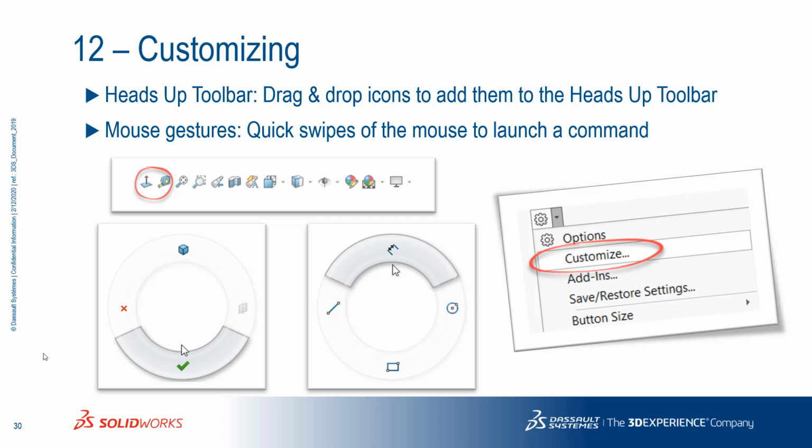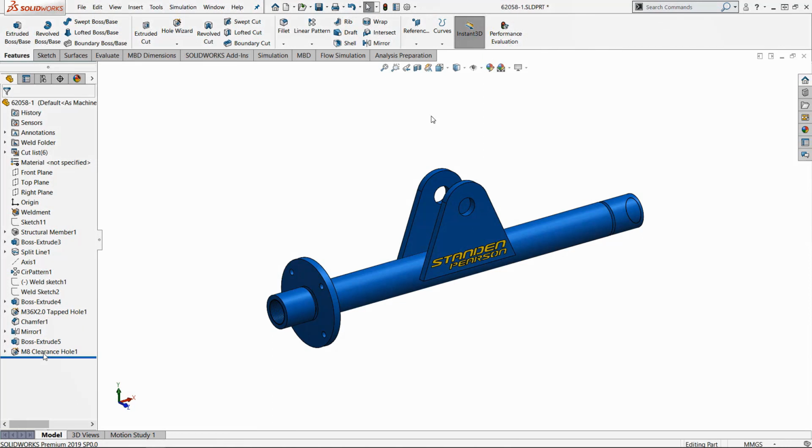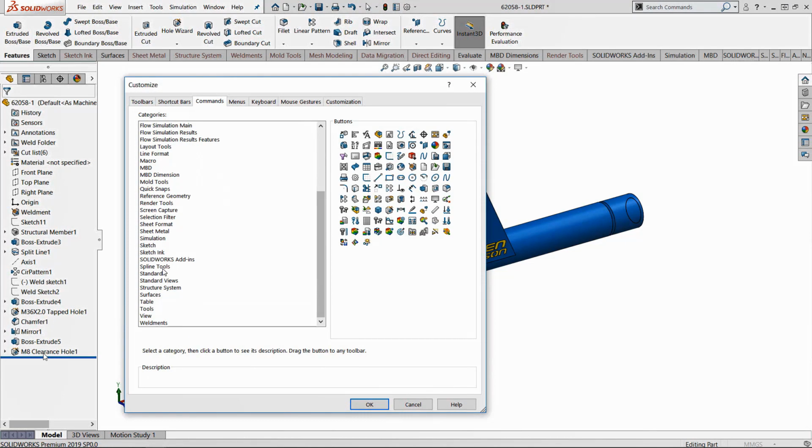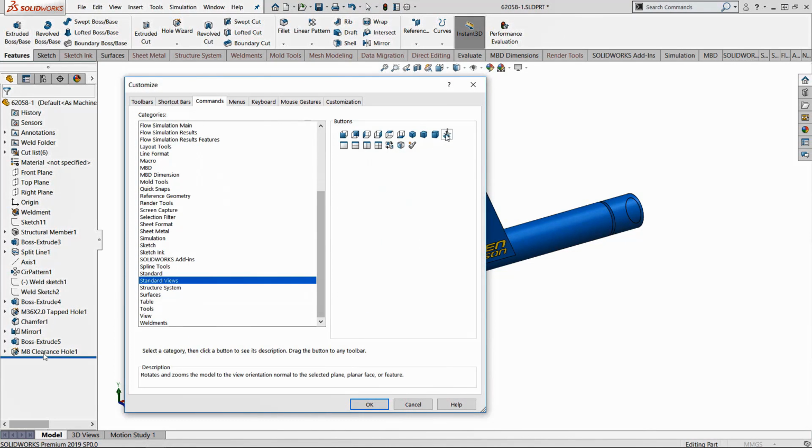Customizing, let's talk about customizing this. So I'll share with you how to customize the heads-up toolbar, and I'll also show you mouse gestures. Mouse gestures are great because you can model very quickly with just wiggling your mouse. All right, wiggle your mouse and just swipe over a command, you don't even see it. So I like to do customizing of the heads-up display to get a couple of commands, maybe normal to or measure. Right, so I find that command, customize...